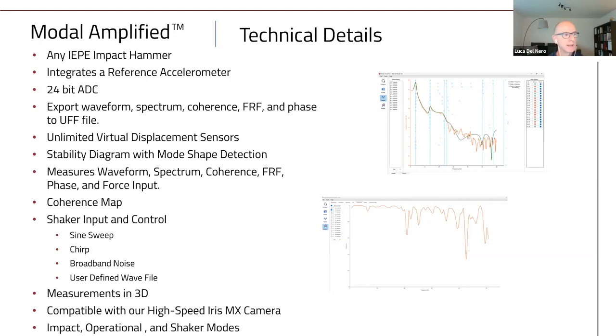We work for household appliances, and typically the situation was to set up standard systems with several accelerometers and multiple bump tests for development of new supports, new components, or to solve existing problems. So, for example, going in the field, in power production plants or refineries, trying to figure out what could be the mode shape or the behavior of a support and why that support went in resonance and failed. So we try to develop new concepts using modal analysis, with bump tests or shaker tests, followed by finite element calculations. The goal was to create new and more reliable parts.